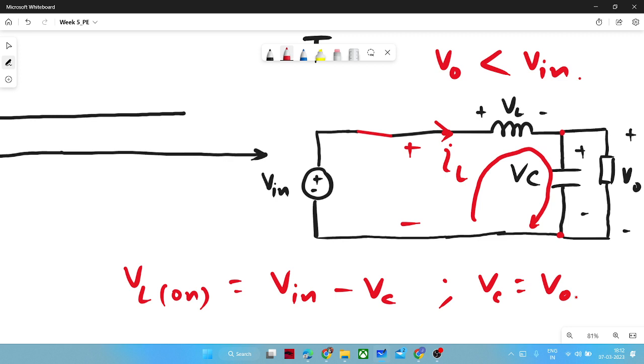The purpose behind connecting inductor and capacitor is just simple, to remove the ripple, right? The inductor is here to remove the ripple from the inductor current. Okay, we want a smooth inductor current like DC inductor current. We do not want any ripple. I will plot the graph of inductor current, and then you will observe that it is kind of not constant.